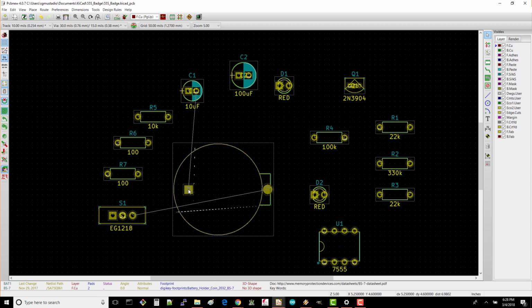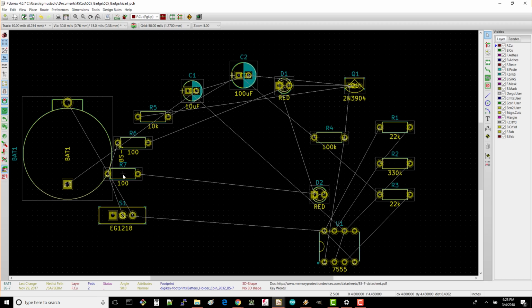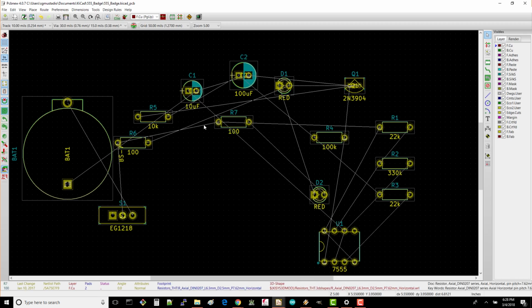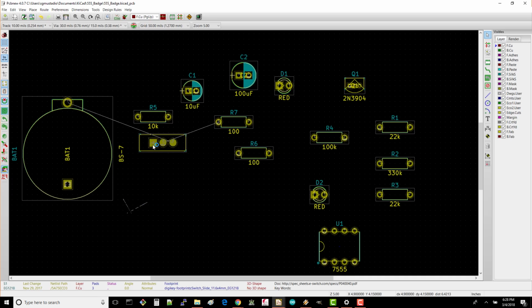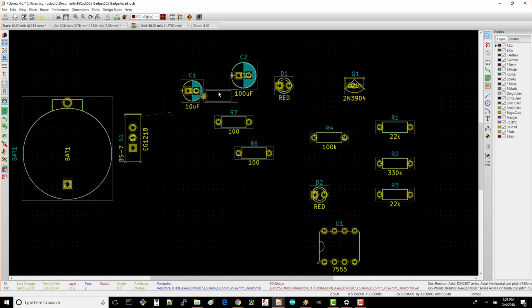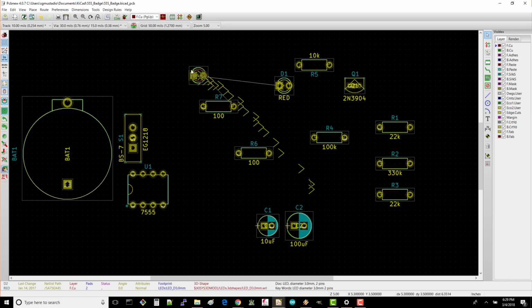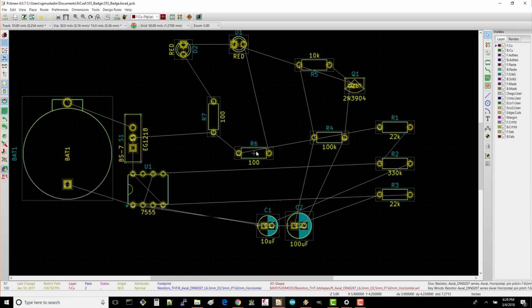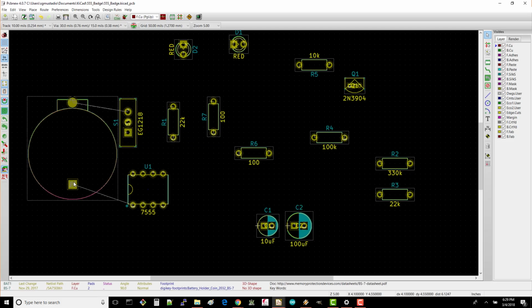Each time an air wire crosses over another air wire, you'll likely have to move that trace to a different layer. You can't just cross them on the same layer because you'd create an electrical short between two nodes that aren't supposed to connect. The idea is that you want to minimize the number of times you have to move to another layer. On very complicated boards, 2 layers won't be enough, so you'll need to use a 4-layer board or a 6-layer board or even more. But we're going to try to do everything with 2 layers.